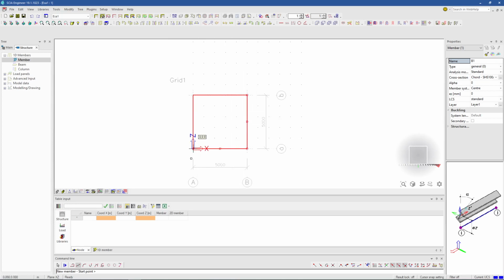This is a four-sided structure or parallelogram. Putting a support, we fit the pin support with a hinge support, with a sliding support here. From our analysis or observation, this structure won't be stable. It will surely fall under its self weight or deflect to the right or to the left.